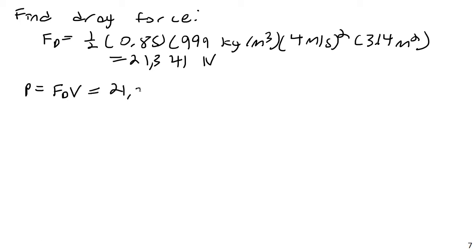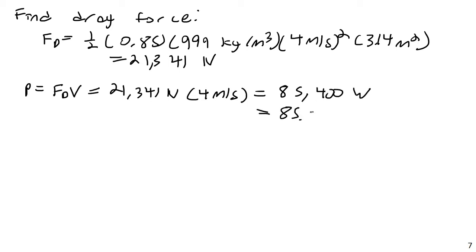That is 21,341 newtons times a velocity of 4 meters per second, and this will come to a value of 85,400 watts, or more commonly 85.4 kilowatts. We could also convert that to horsepower if you wanted, but we're given this in metric, so I'm just going to keep it in metric as well. So 85.4 kilowatts. Quite a bit of energy just to overcome the drag force of pulling this log along.